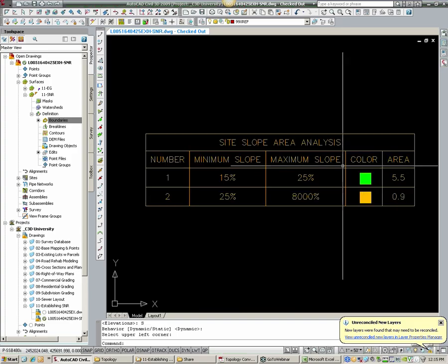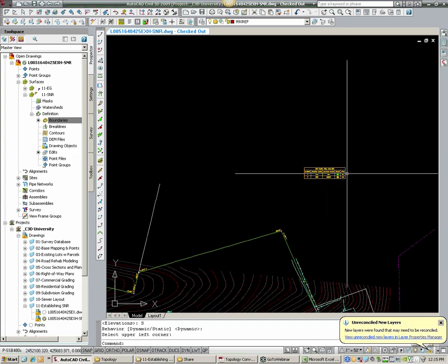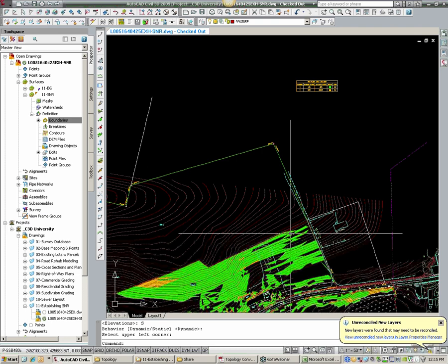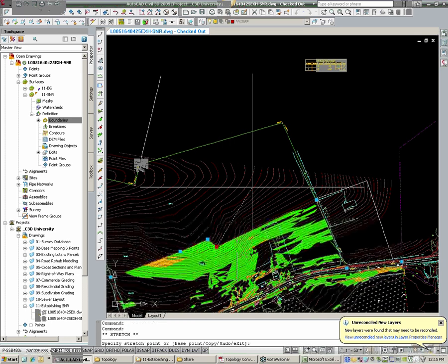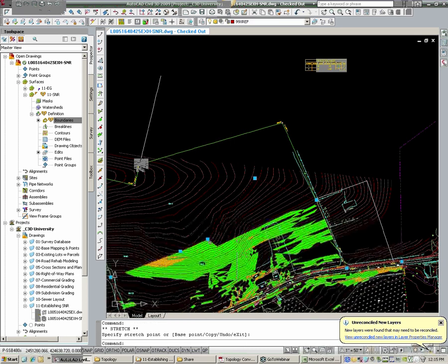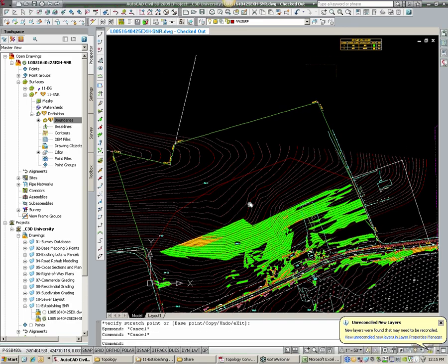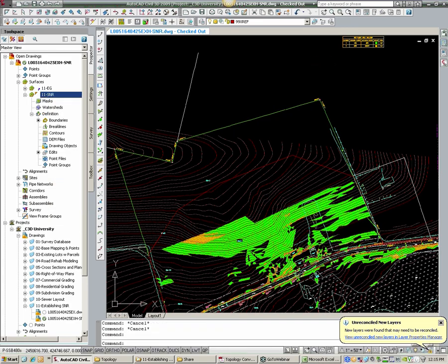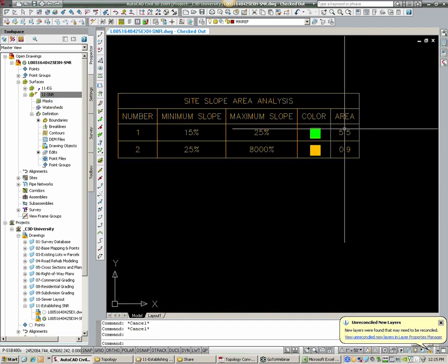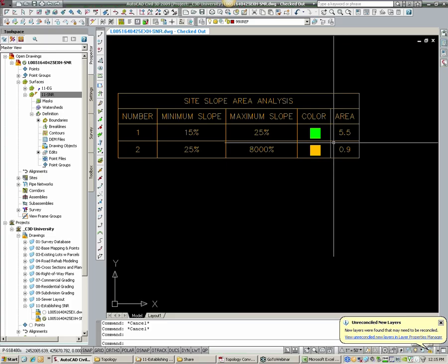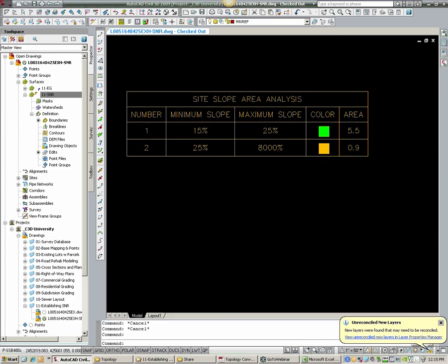Now, be cautious with this table. I've noticed a little glitch in the software. That area is correct, but you would assume it said dynamic, right? That if I take this boundary, bring it up here, and move it around like this, which could happen, then I have to rebuild my surface. So it gets in more colored area, more triangles. You would assume this table would automatically update. It doesn't. I think that's a glitch in the software.